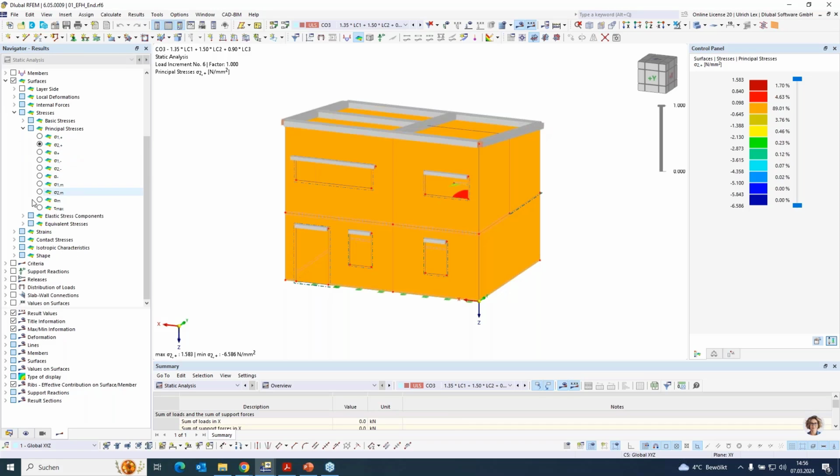You can take a look at these strains, because when the strains are too big, it is a hint that cracks exist in the masonry. I showed it in a webinar before, where on the sliding slab on the edges, cracks are here.